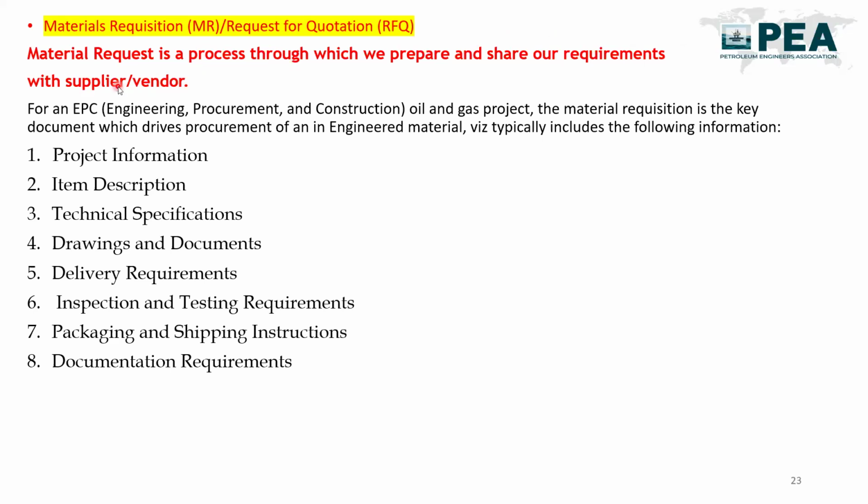We need a stem diameter. What is the stem diameter? What should be the stem length we should take? What will be the grade of the material? What will be the RTD sensor stem material? What will be the RTD head material? What will be the connection size? All those things we need to give to our supplier or vendor.